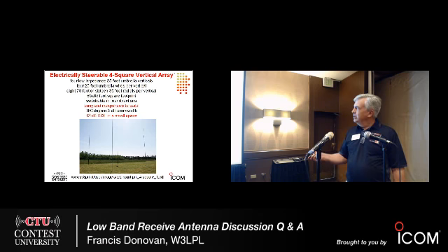IV3PRK built a small 4-square of low impedance verticals, 25-foot verticals with umbrella wires. He used a small number of radials, 65 feet by 65 feet, easy and inexpensive to build, and his website describes it. He had some difficulties with the performance of this antenna, probably because he had a number of really nearby RFI sources.